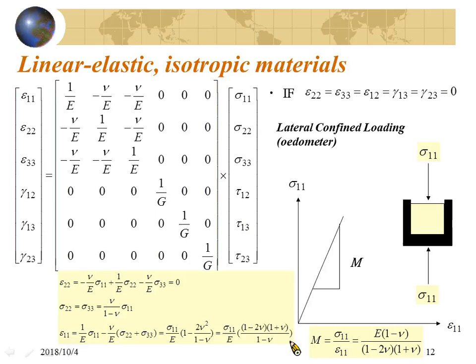Another way of thinking: for this case, you will have a normal stress and you will have horizontal stress as well. Horizontal stress will produce negative strain in the vertical direction to compensate the displacement caused by sigma 1.